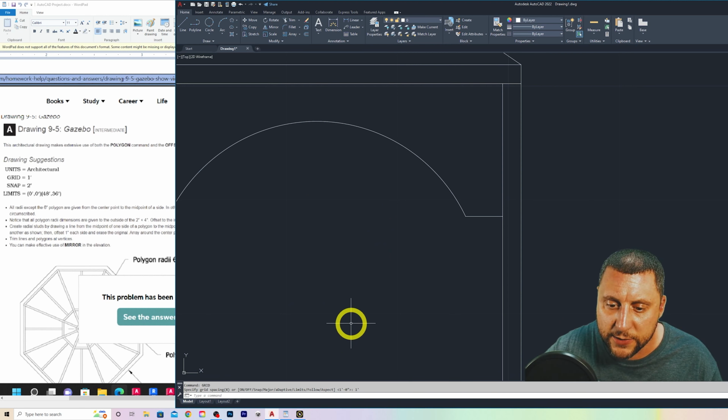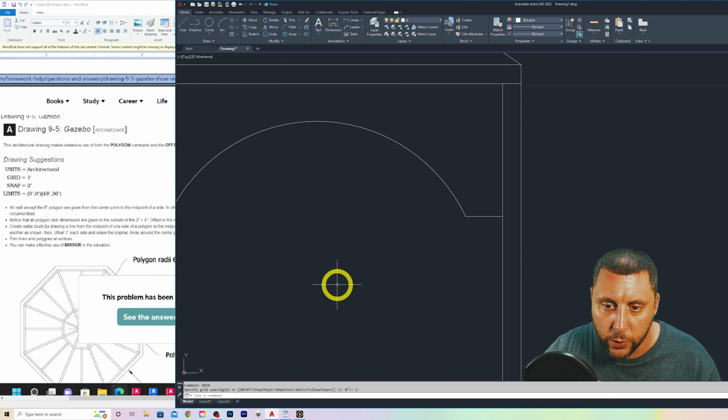If you don't type a size in there and you leave it by default, the grid is actually dynamic, which means that as you zoom in further, there are more and more boxes that it breaks up into, okay? So that's up to you if that's something that interests you and that you want to set up in your drawings, have at it.